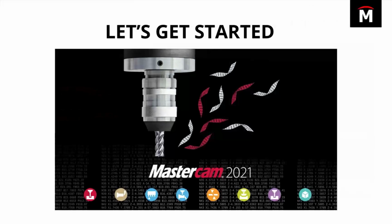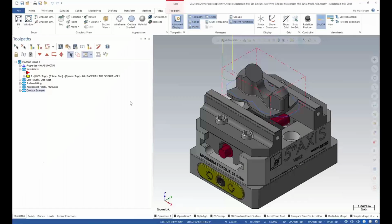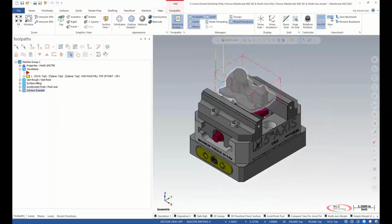First thing I want to talk about inside of Mastercam is software designed for optimum productivity. When I think of optimizing productivity inside of Mastercam, the first thing that comes to mind is one of the simplest things that come with the very basic package, and that's view sheets. We're talking about 3D Mill and Multiaxis, but the reason I bring up view sheets is because it optimizes the ability to change your planes, levels, and any other views that you want within Mastercam. Typically, if you're working multiple sides of a part, instead of going through your managers over and over, you can simply go through your view sheets.